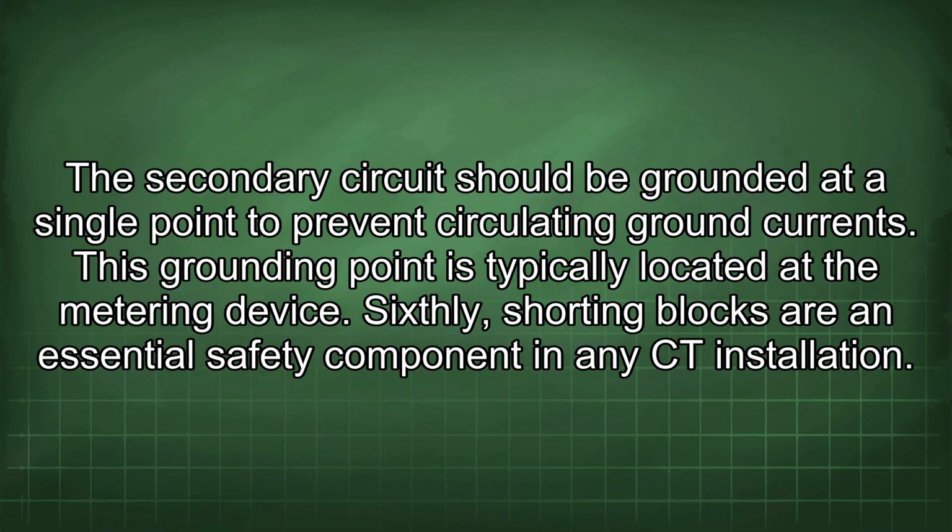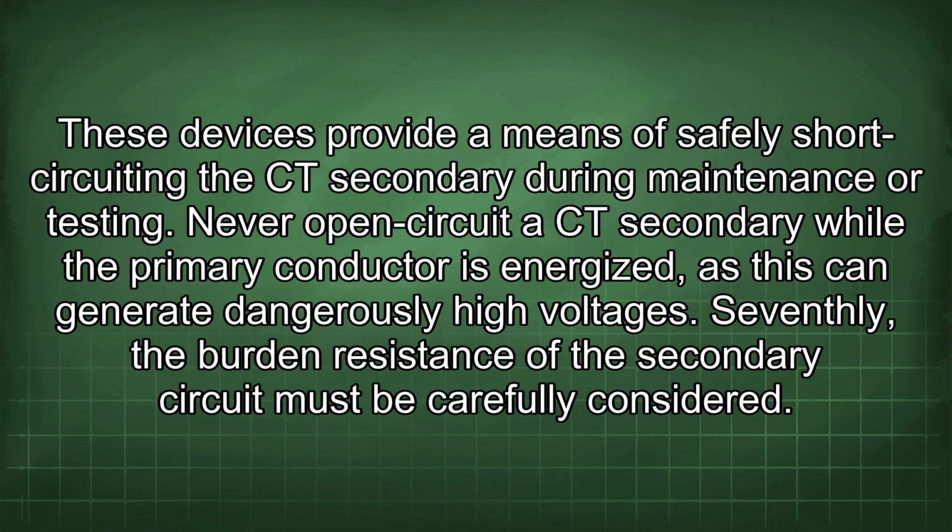Sixthly, shorting blocks are an essential safety component in any CT installation. These devices provide a means of safely short-circuiting the CT secondary during maintenance or testing. Never open circuit the CT secondary while the primary conductor is energized, as this can generate dangerously high voltages.